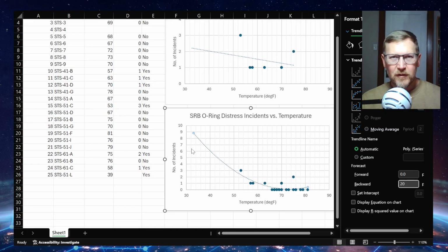They're scaled appropriately. One of the things I see a lot with stress engineers is they will plot a couple different examples of, for example, a stress plot on a structure, and they use completely different scales. And while the automatic scale is great to save you time, it doesn't always help you understand the issue at hand, especially if you're comparing one versus another and you're using completely different scales.